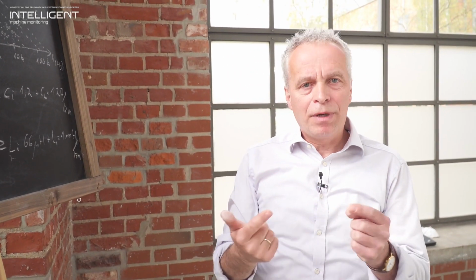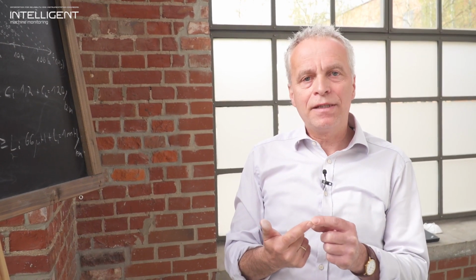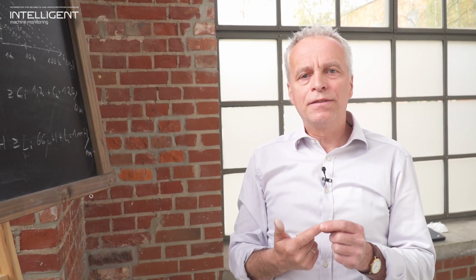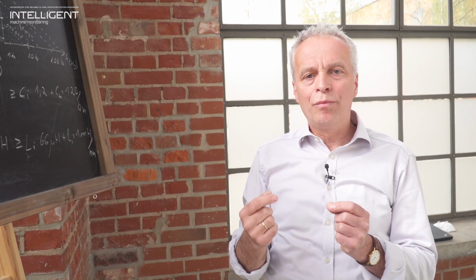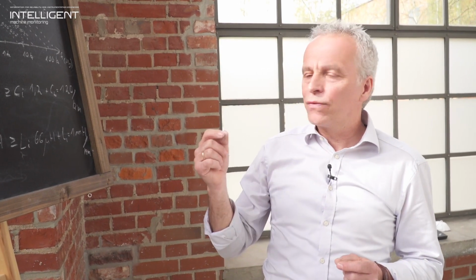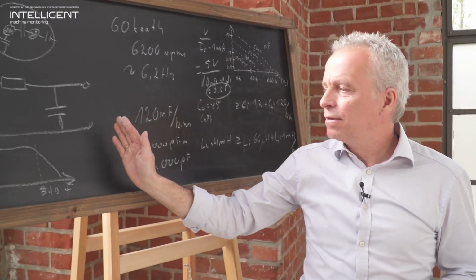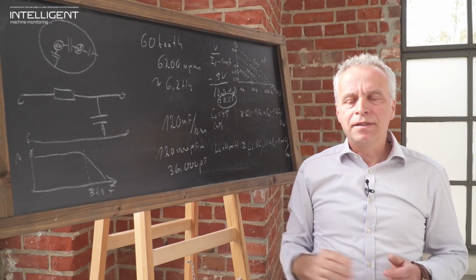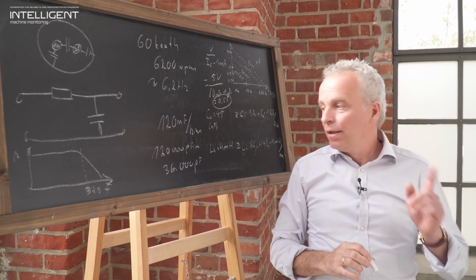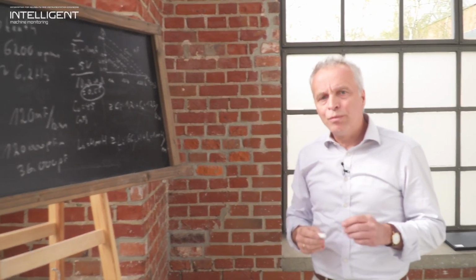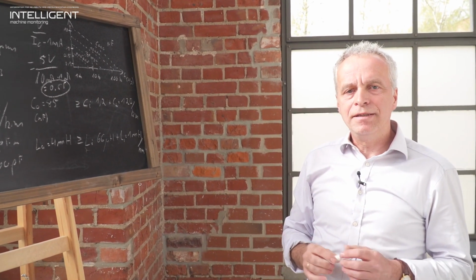Each cable, by the physics, has a capacity, and together with the impedance or resistance of the input card it builds a low-pass filter. And we have to limit the cable length in order to have a decent monitoring for all the signal analysis. The next point I want to mention is regarding intrinsic safety.